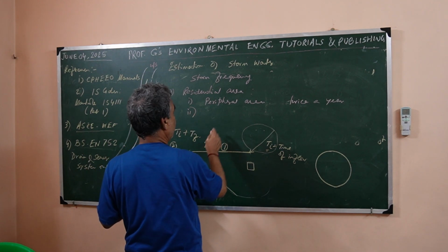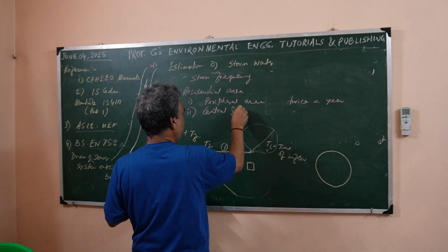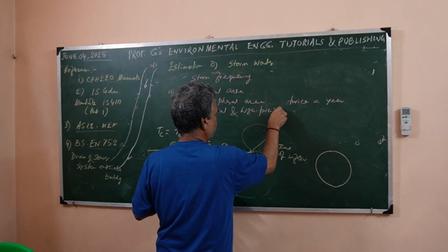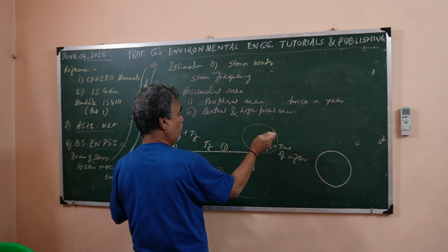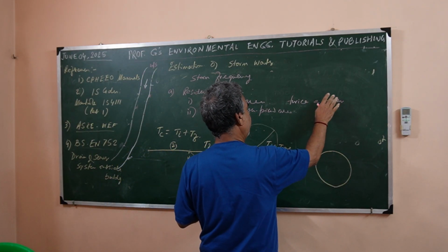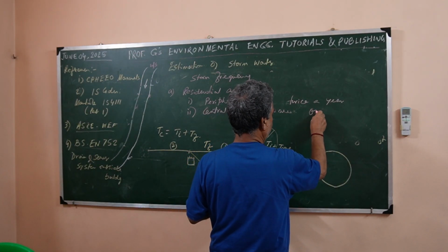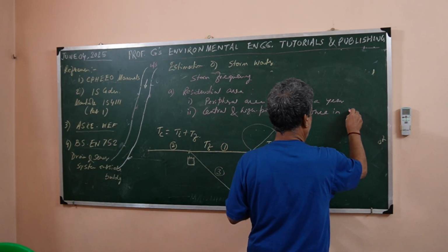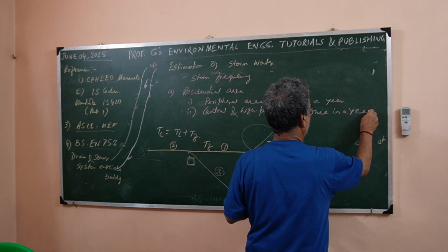Central and comparatively high priced area, where the frequency of flooding should be less. Here, if the frequency of flooding is more, it does not matter much, but here it matters. So here, once in a year, you consider.